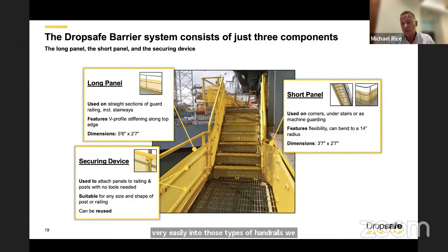We often have it reported, especially from land-based facilities, that many dropped objects occur when people are walking from the work shed where the tools may be kept to the workplace where they're going to do the maintenance of the equipment. Quite often that means going up and down staircases, where you would have one hand holding the handrail, and you may not be paying so much attention to the equipment that you're carrying. So staircases are actually a fairly significant risk spot in most facilities where a lot of dropped objects occur.